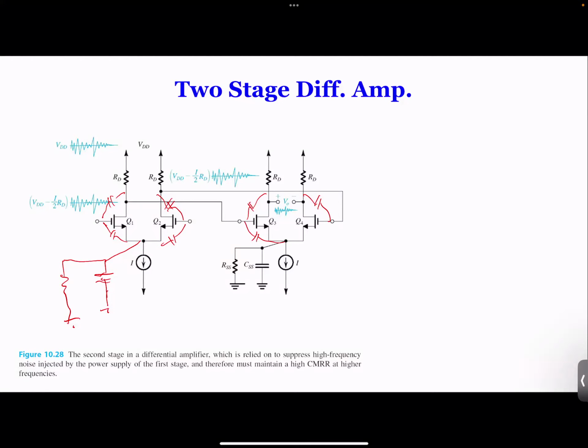And you will see noises like this. Some of them have a regular frequency, like a 60 hertz noise, you can see it. But for some high frequency noise, sometimes they call it white noise, they pick it up from the environment. Some other switching devices, lights, these days we all have LED lights. The LED lights use power electronics, they use switching power supply. Those switching generate the noise. We don't hear it because the frequency is high, typically in the hundreds of kilohertz, but it can be picked up by a receiver, okay?